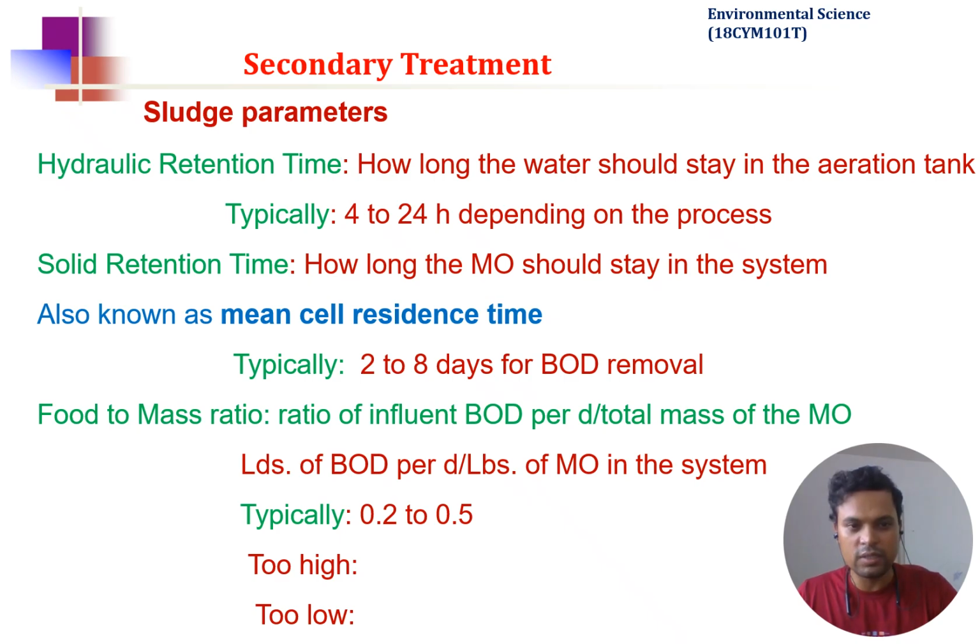Okay, solid retention time, which is basically how long the microorganisms should stay in the aeration tank. Typically this is about 8 days for the BOD removal. So you can reuse them 2 to 8 times, not more than this. After that you should remove it and then try to grow new bacteria.